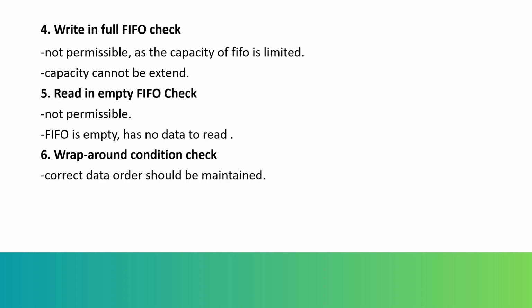For the write in full FIFO check, when our FIFO is already full and we are trying to write something in it, the FIFO should not accept that data, as its capacity is limited and it's already full. The capacity of the FIFO cannot be extended. So we have to check whether this scenario is working properly or not.